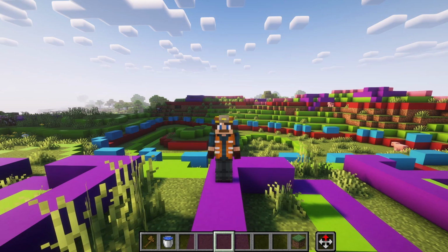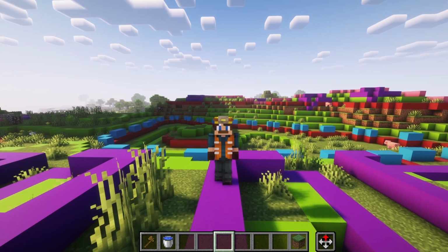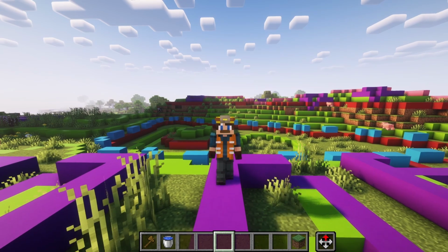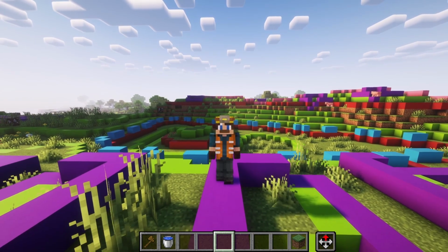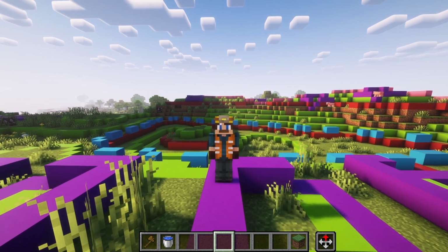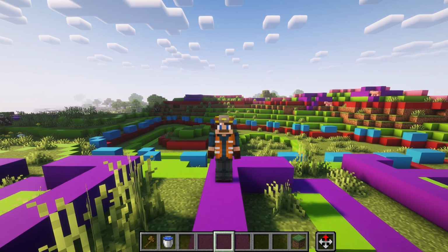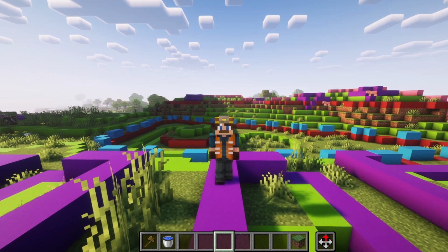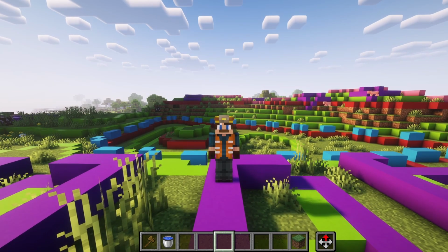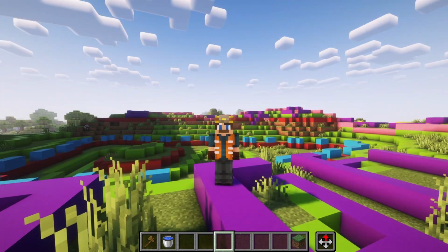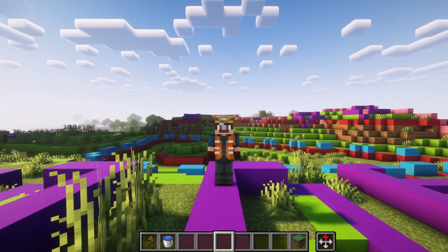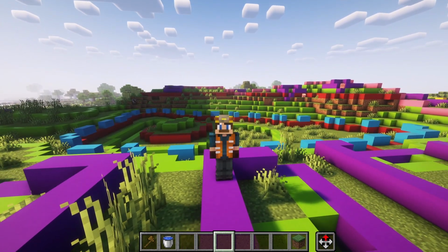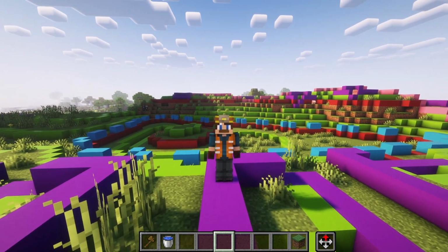Similar to a lake or a pond, they always maintain water with the additional capacity to temporarily store runoff during and after rain events. As for their function, they manage the water quality by slowly releasing the water through a controlled outlet, but also improve the water quality by allowing pollutants to settle to the bottom and the vegetation around to help with the filtration. Typical uses of a retention pond are in areas where water needs to be retained for longer periods, like in developments with space for water features, such as the one here.